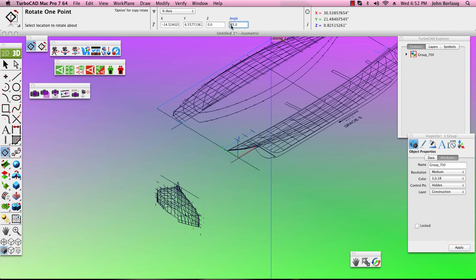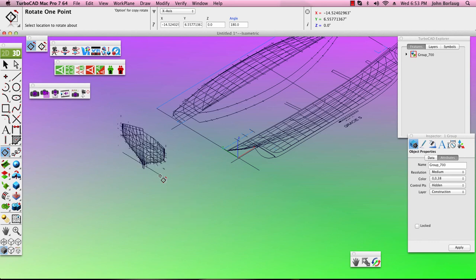So now with that rotate available, let's just modify that to 180 degrees. And then pressing decimal or comma over in Europe, that would be the comma, and enter, and we see that the angle is highlighted in gray, but it's still asking for a signal where to rotate around, and we'll click the rotate now, and there we have a right side up boat view, even though we don't have things aligned properly. So let's pause the video there.